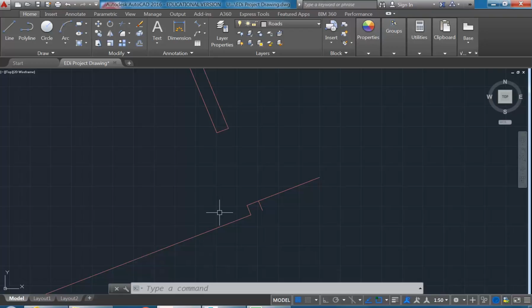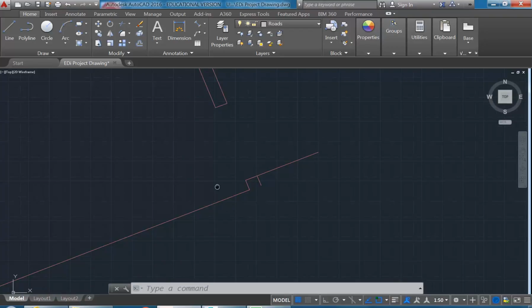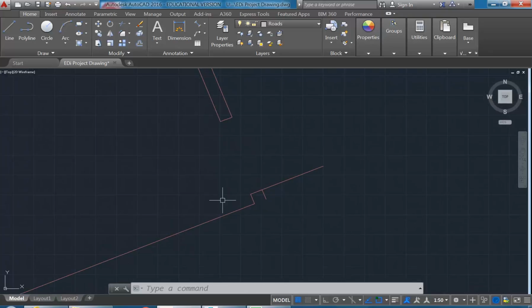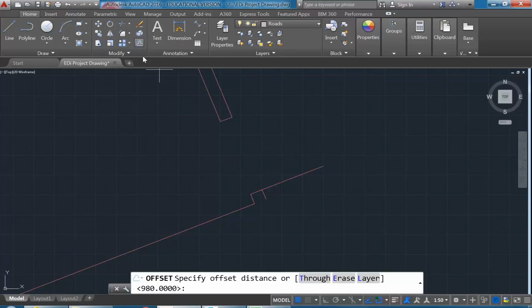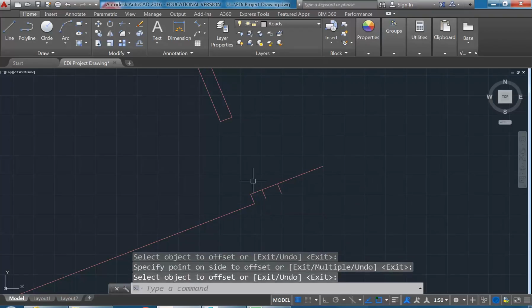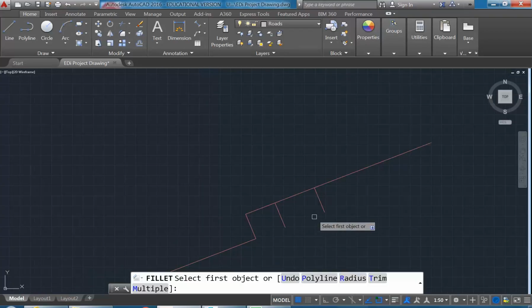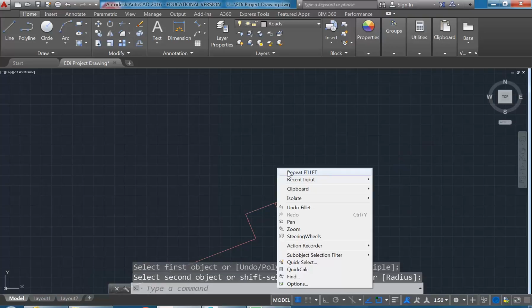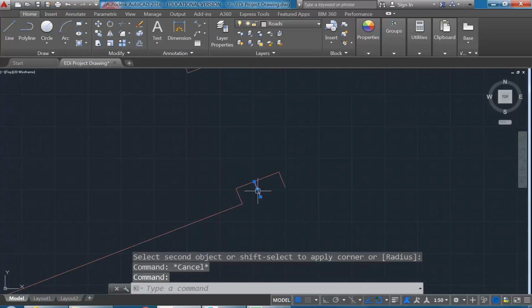So there's one on the corner there. Yeah, just next to the door. Okay, so for now we can just assume the thickness. Maybe we'll go and take a measurement in a while, but for now let's just assume it's 350. So I'm going to offset 350 from this line here, and then I can just use fillet to join those together and remove that line.